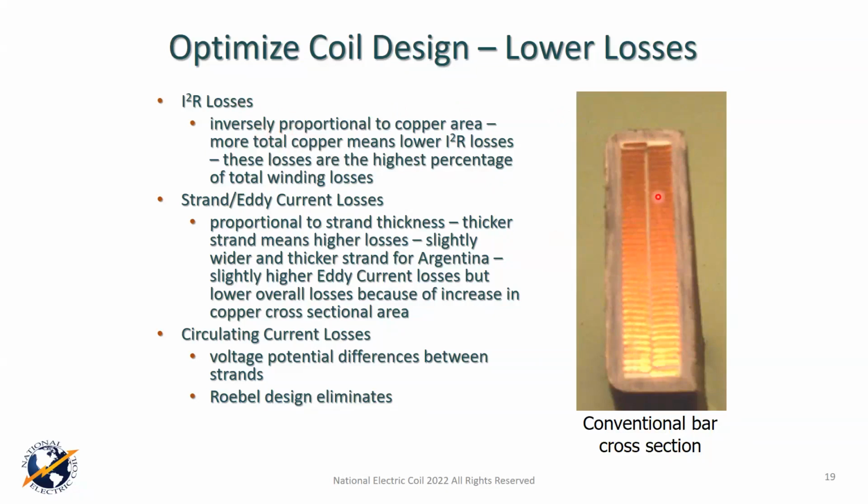The more copper you have, you can decrease the temperature at the existing megawatt rating. But if you put in increased copper, you can get a higher rating, though it usually would take you to a little bit higher temperature as well, if that makes sense to you.